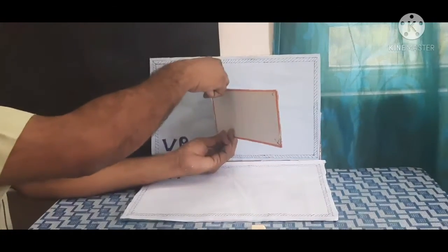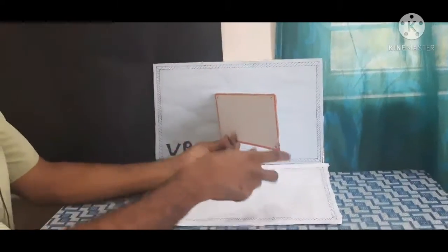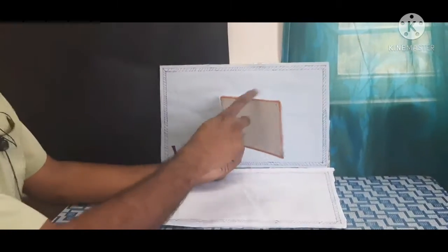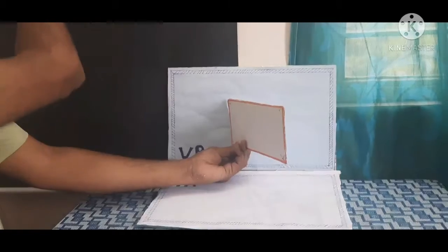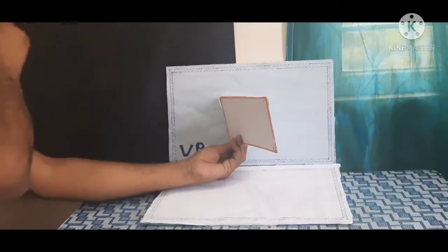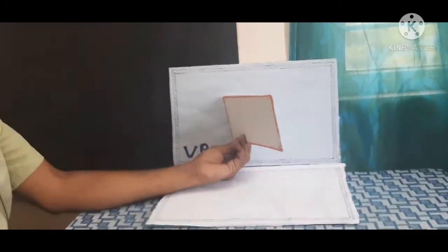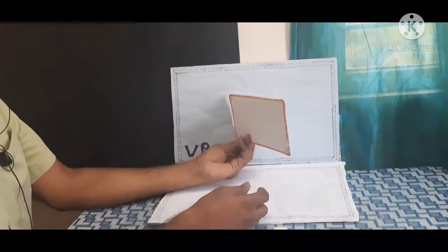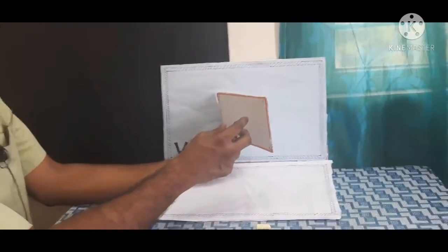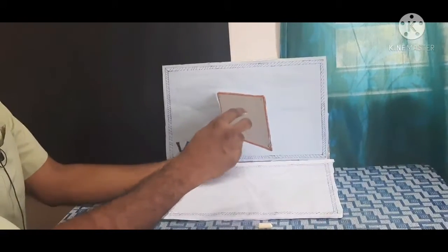But if this inclination is not given, instead what is given is that the front view comes as a square. What is given in the second sentence? Project its top view if its front view is a square of 30 mm long sides. While viewing for the second stage, its front view will look like a square.